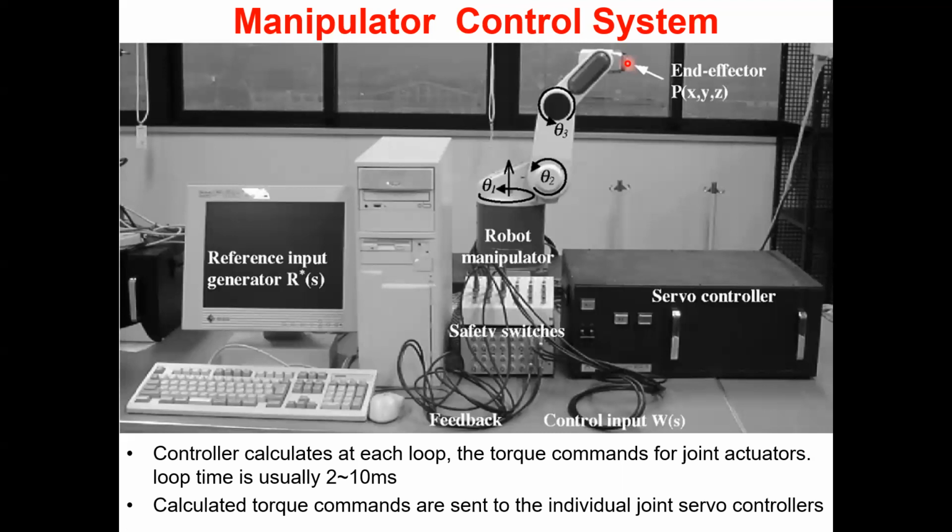For a gripper you need to control the rotation before you grip. But if it's a welding torch, any direction you can use because it's a symmetric tool application, okay? So therefore, there are a lot of robots where the number of degrees of freedom is 5, not 6. So this is one of them.